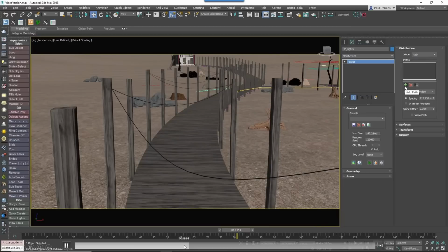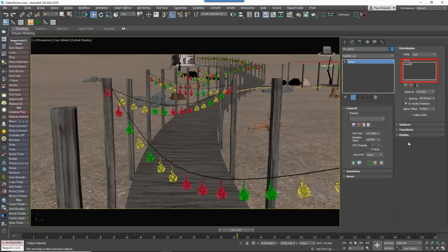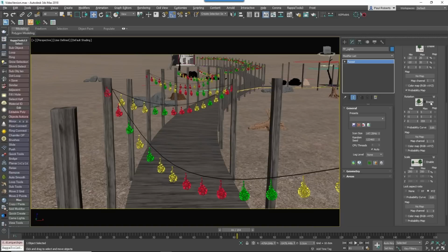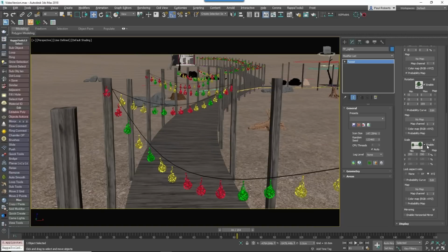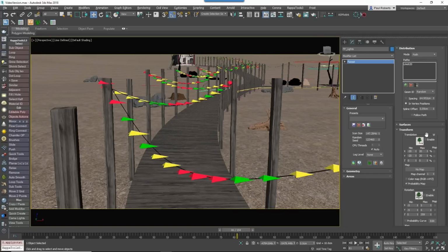You just basically pick a spline from the scene and you can change the spacing between objects. It's like a little bit of RailClone in Forest Pack. I've got control for offsets, or I can put them on vertex positions. You can use multiple paths. There was something similar in Forest Pack previous to 6, but it wasn't parametric. Now, if you change the spline, if I change the spacing at any point, the whole thing updates, no problem. And you can still use rotate, scale, and transform variation if you want to. You can choose to follow the path, or you can choose to just randomize it.